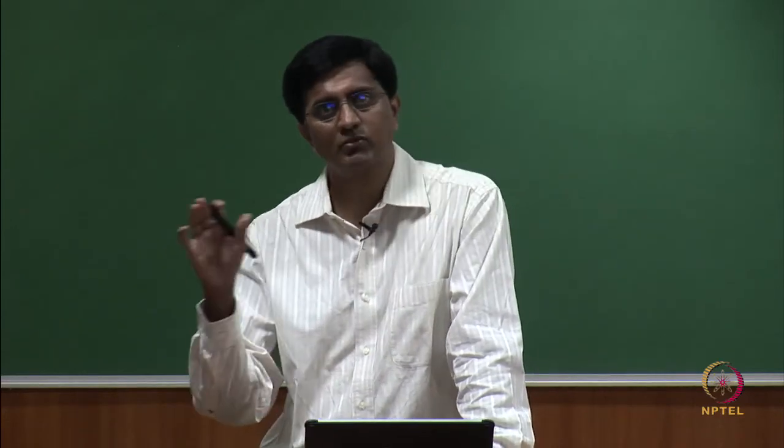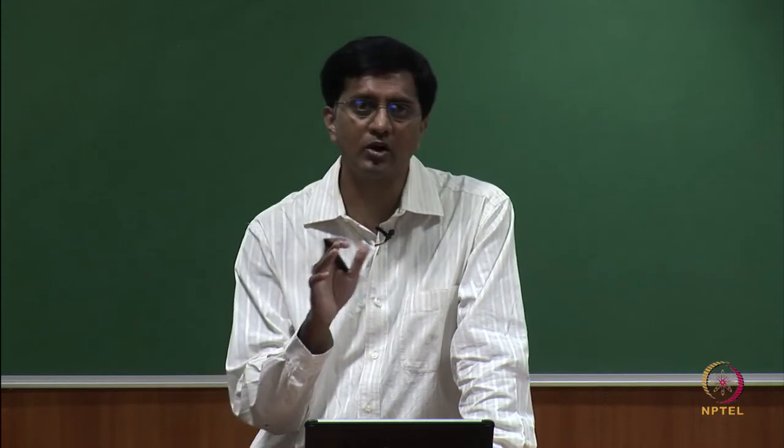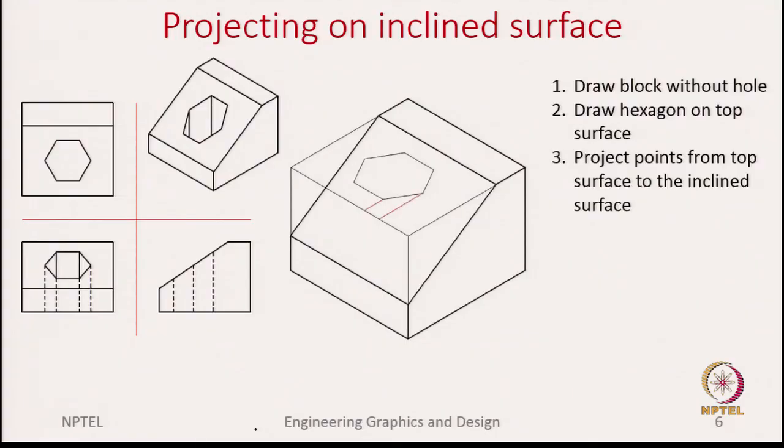Instead of going to the side view, we can also go into the front view. So, as you can see, we have drawn lines in the top view, then the front view and again the inclined surface. And then lastly, we just need to draw vertical lines to project the depth. So, with these we capture 2 points.